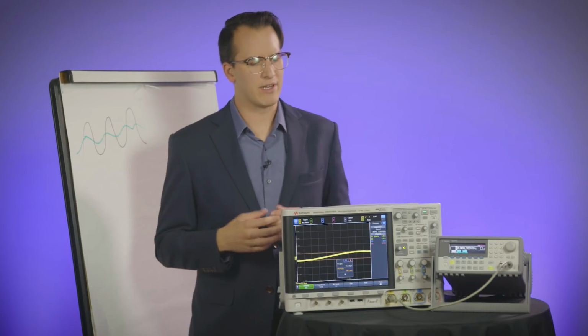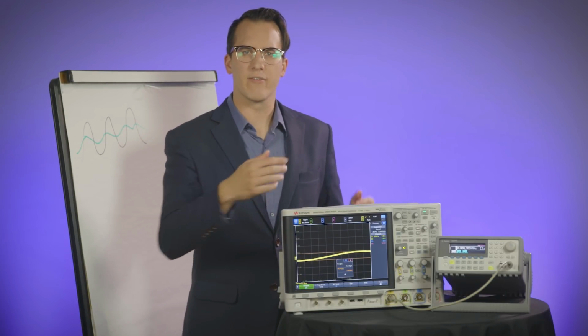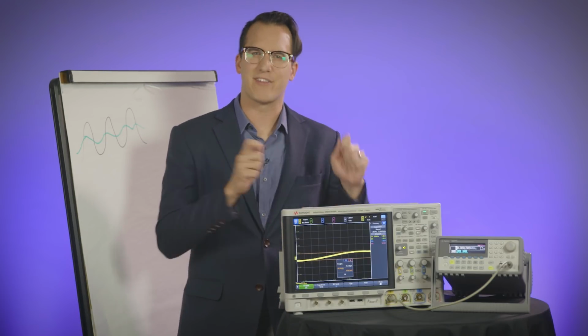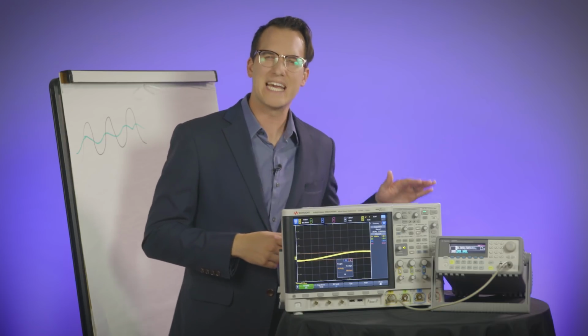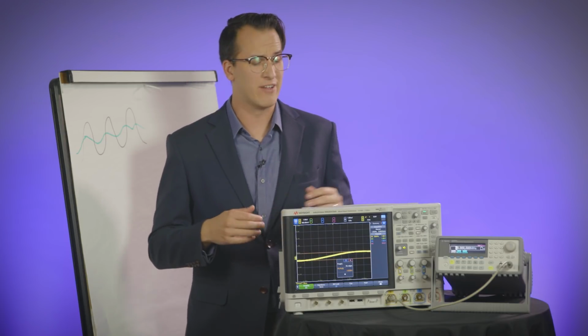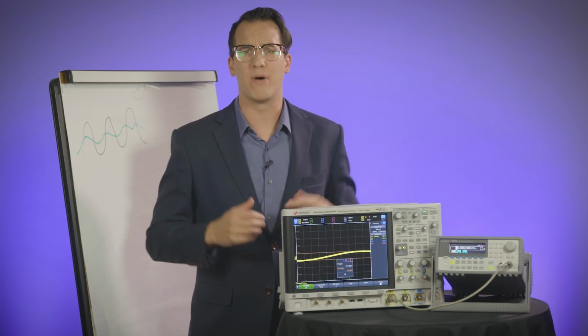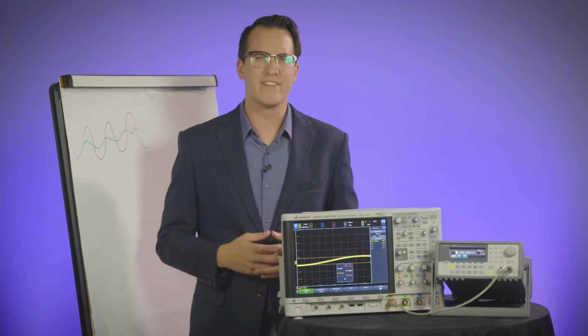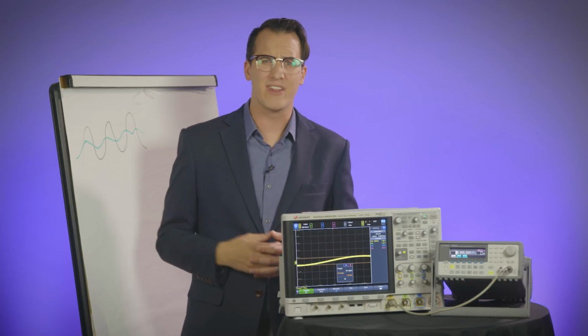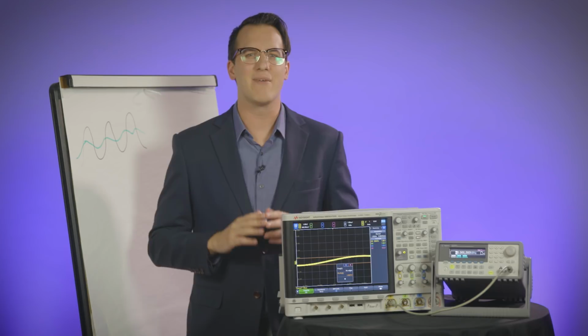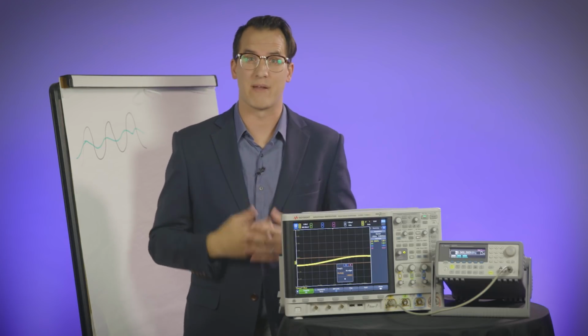So here's what's happening. As my signal increases, my scope tries to increase, but with that 20 MHz bandwidth limit on it, it cannot quite get there fast enough, and it can't just magically jump up to the new voltage value. The speed that the scope adjusts to the change is dictated by its bandwidth. So you can technically measure a frequency that's higher than the max bandwidth of the scope, but you cannot measure an edge speed faster than the max bandwidth of the scope.